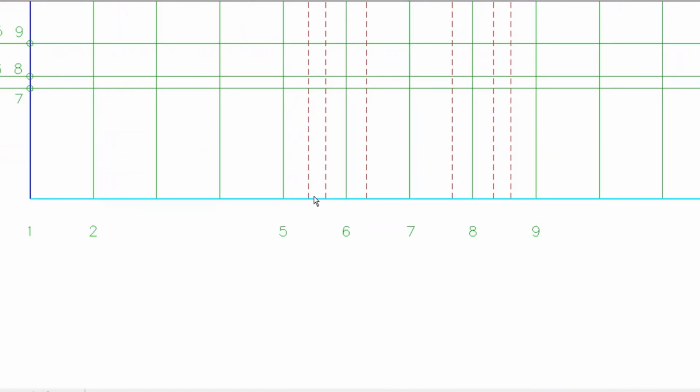And there you can see I marked them down on the base and then I just took the construction lines up. So I'm just trying to differentiate between the two types. Okay, that's why I'm using these red broken lines. Now I'm going to do something higher grade. Okay, that's only applicable for the grade 12s. Okay, to show you how to accurately get these lines without measuring on the top view with a ruler.